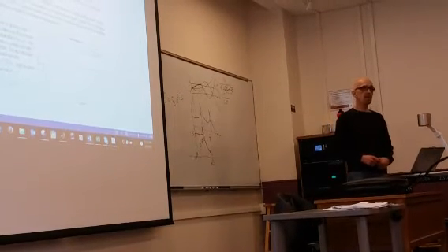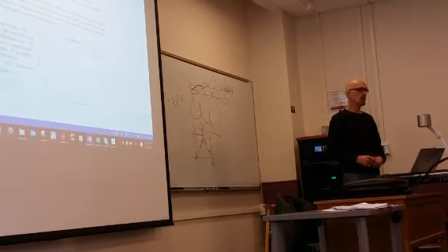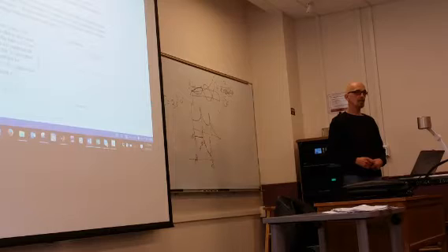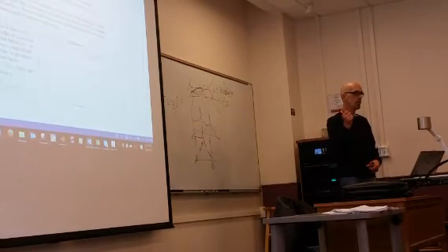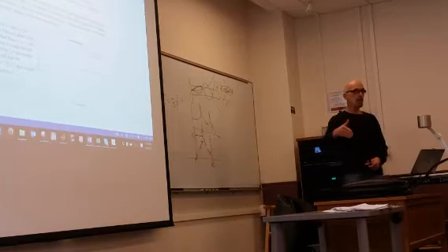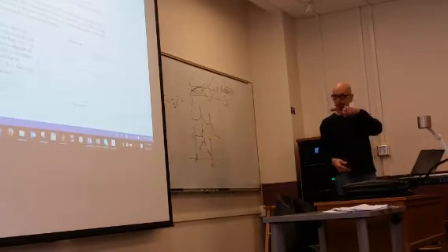So this is a huge reason for doing controller design in the frequency domain: you can handle time delays like that. All you do is modify the phase plot by omega times the delay d. So it drops down.